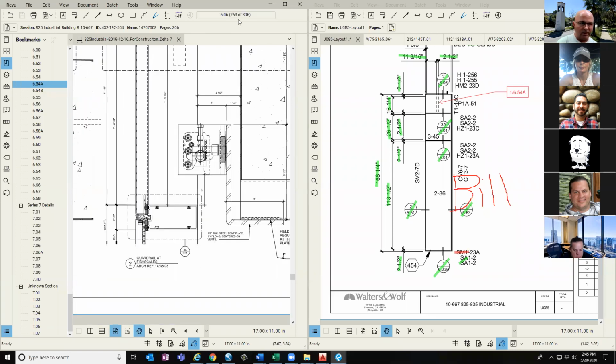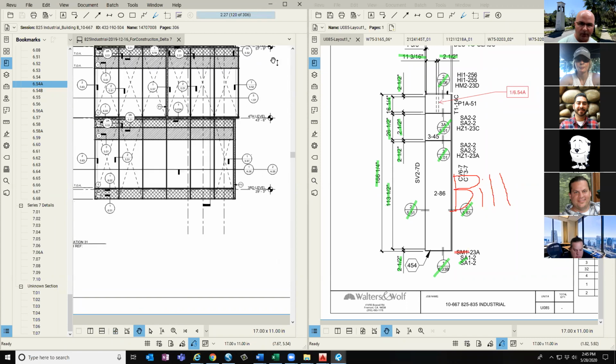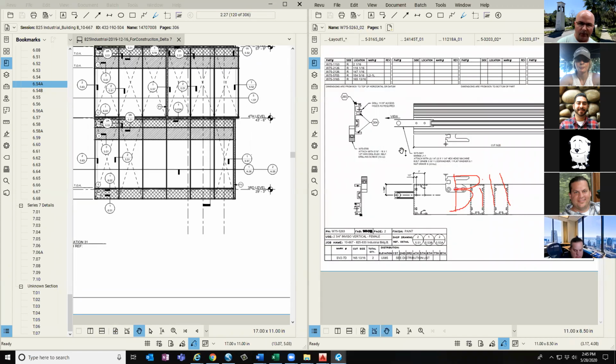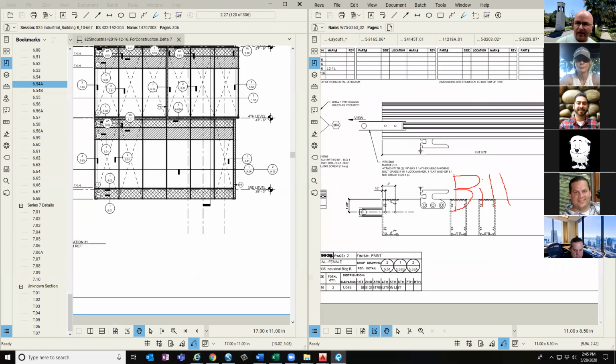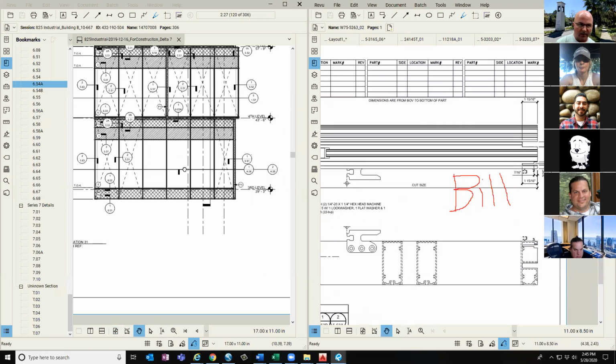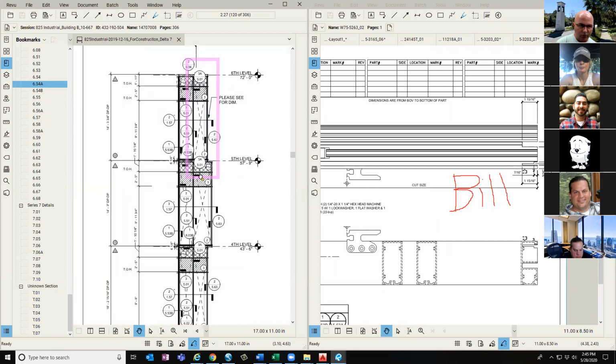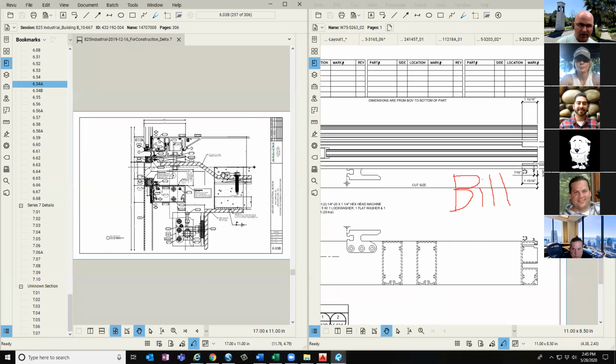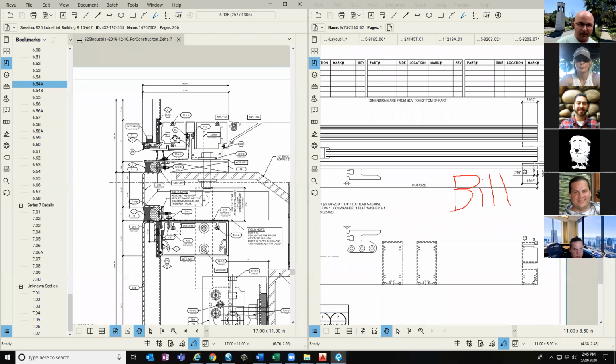So now I'm going to look at what's happening for the vertical at the bottom. My split vertical, for example, I've got the 1 and 15/16 notch at the bottom, and that should be the notch that I'm expecting to see on the wind load sill condition. So that's a typical wind load sill. I'll mark all of those. I may mark them up one by one.